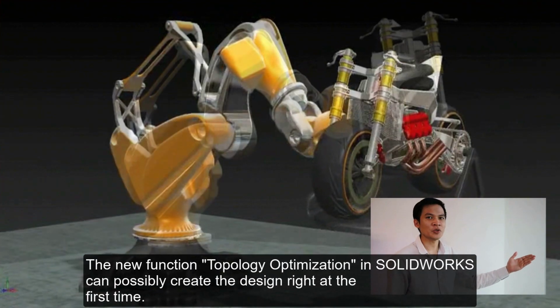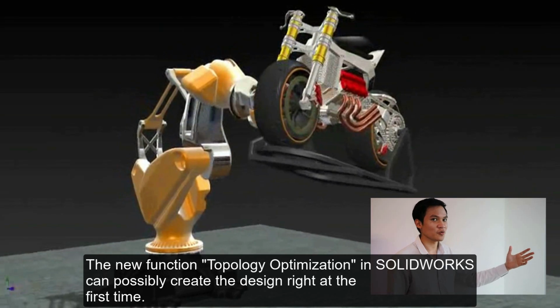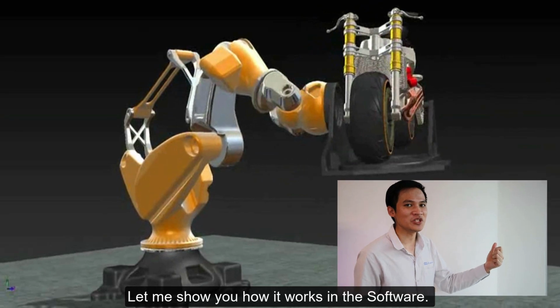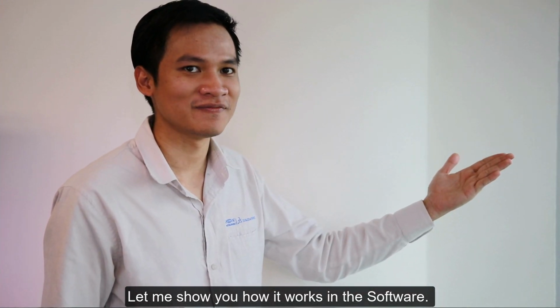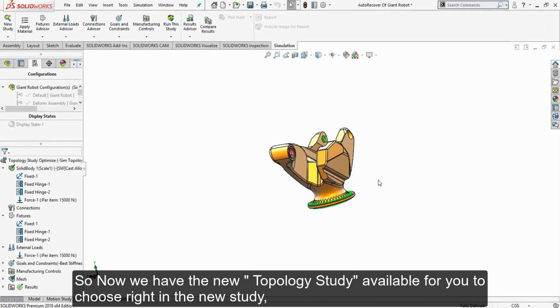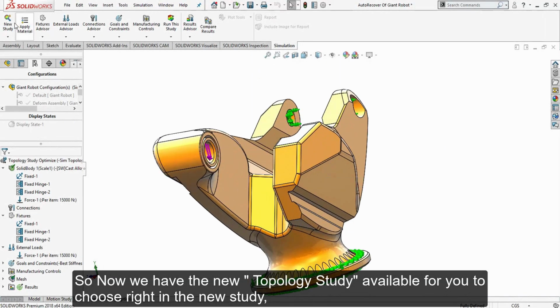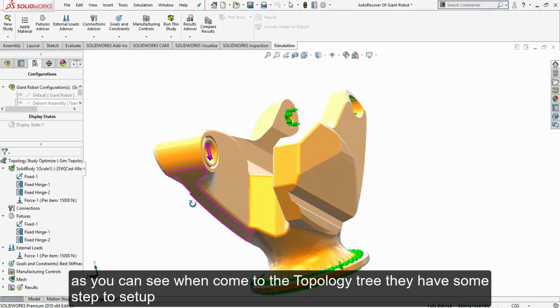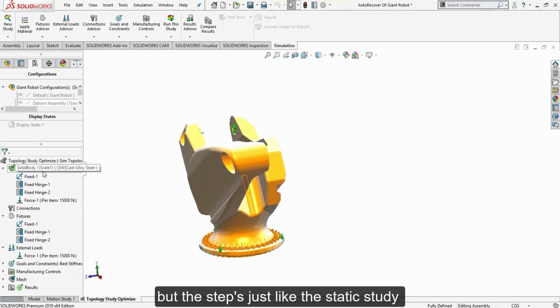The new topology optimization function in SOLIDWORKS can possibly create the design right the first time. Let me show you how it works in the software. So now we have the new topology study available for you to choose right in the new study. As you can see, when it comes to the topology study, there are some steps to set up, but the steps are just like the static study.